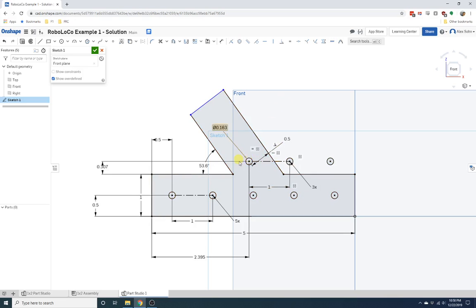The default state for this is that it's in the horizontal or vertical direction, right? So I want to change that. So I'm going to click on this line, and then you notice when I hover over it, it has these constraints, right? So this constraint is constraining it to be only horizontal. So I'm going to click that constraint. I want to delete it. So I'm going to click delete, and it goes away. Notice how these turn blue now.